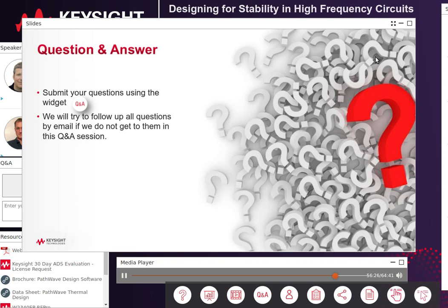After all this studying of loop gain methods and the normalized determinant function method for stability analysis, I finally figured out that these two functions together actually compose the driving point impedance itself. So loop gain analysis can be considered a subset of driving point impedance analysis. Long story short, I now support the primacy of using the driving point impedance or the driving point admittance as the main stability metric, because it can be shown to be composed of both a function of the bilateral loop gains and the open port impedance function, now provided by the new WS probe.